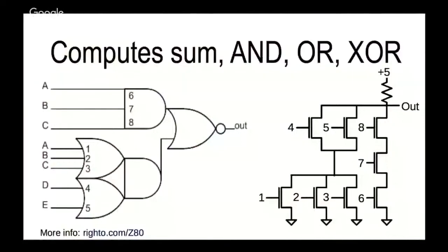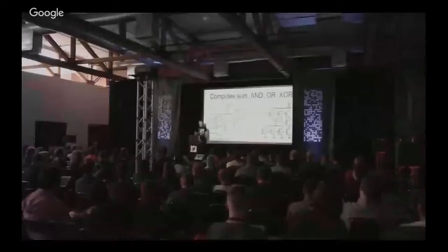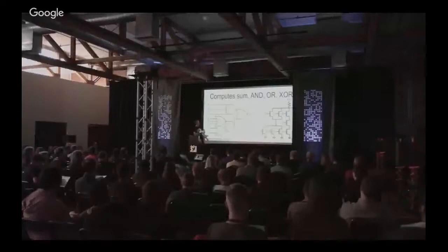These 2 gates you don't require any circuitry for. They're just made by wiring the 2 parts together. So this is one of the ways they made the Z80 much more compact. I won't try to explain what this is actually doing, other than it takes ALU inputs B and C and then computes the right operation all with this one gate.